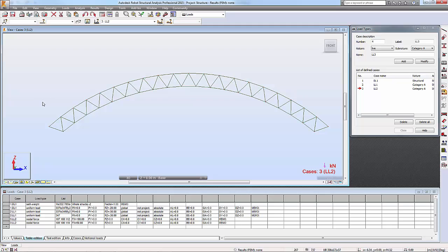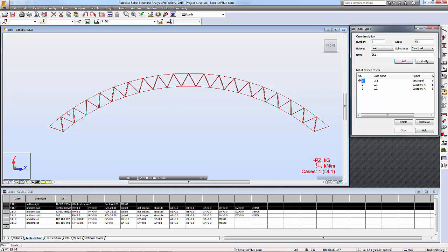So what we need to do is that make sure you are in the select mode, and then make sure that is in that load case 1. So you choose all the nodes by select the first one and hold on the control key and select this one by one. So all the top node.